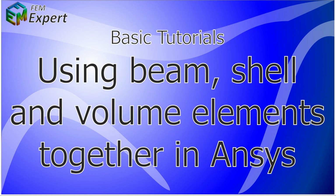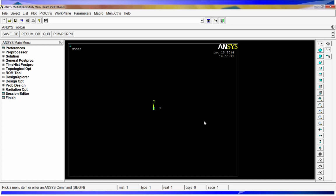Today we will present a basic tutorial in which we will show you how to use beam, shell and volume type elements all together in an Ansys simulation. As usual, we will start with the Ansys interface that you probably already know. In this simulation we will generate a table with a 1 square meter top made of aluminum with 4 legs made of steel. On top of that we will place a cube of steel using volume type elements, and we will see how the structure behaves.